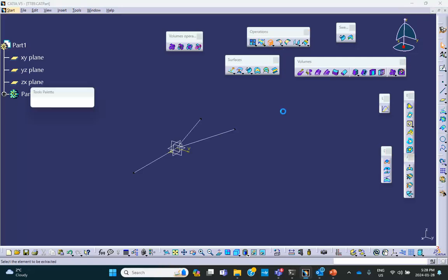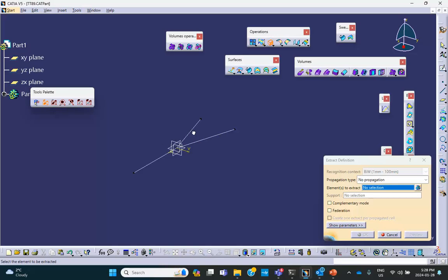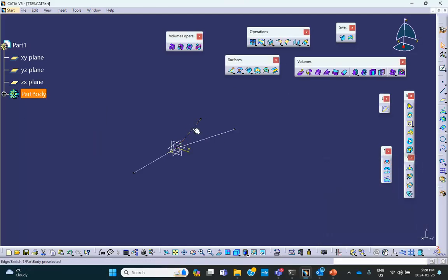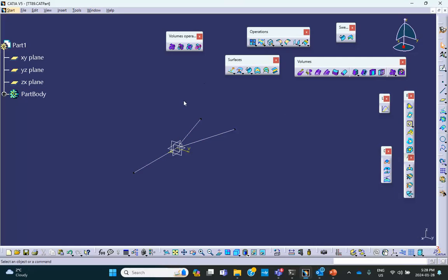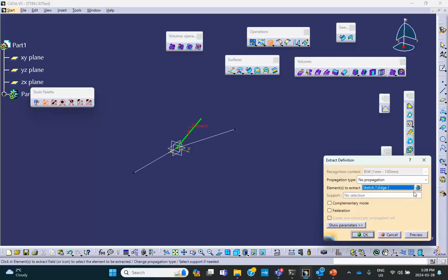You have extract, and I'm going to extract this, and extract that one. Now, when I try to select this, it won't do that. If I had pre-selected these three with the control, for example, it would have taken all 3 of them. Well, I didn't. Cancel. So let me go back here, extract this. Now, if you want to select more, you can click on this group bag and select this one and that one, whatever is easier for you. Close that and say okay.